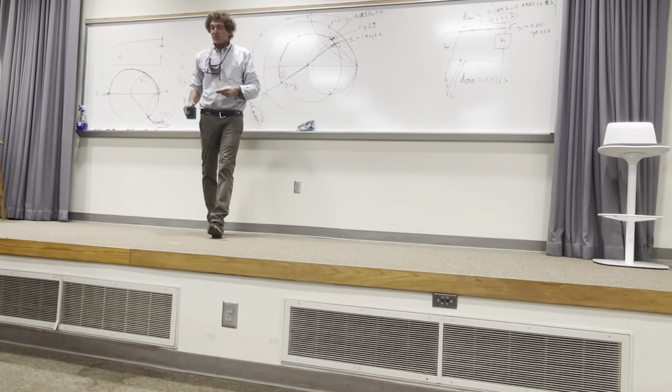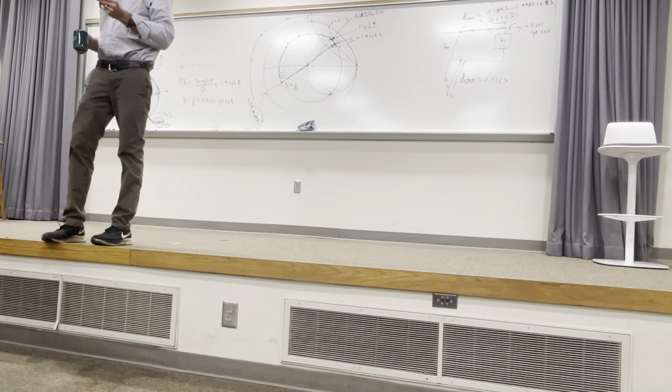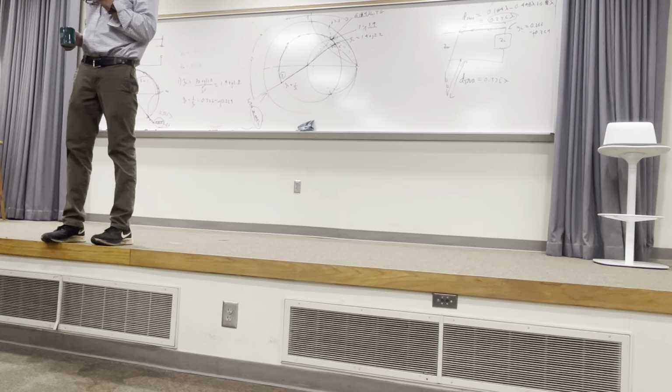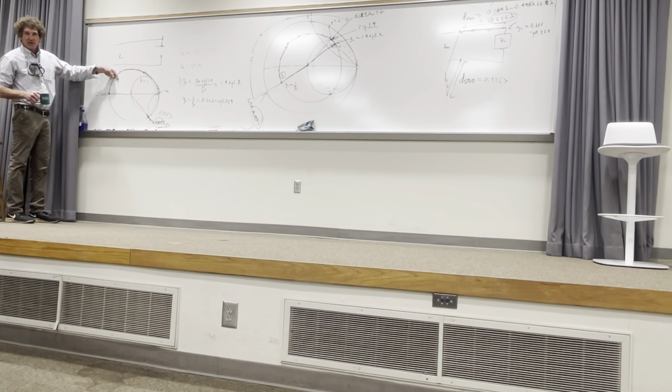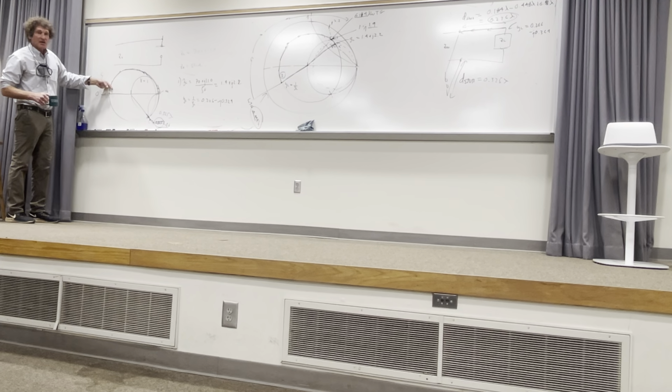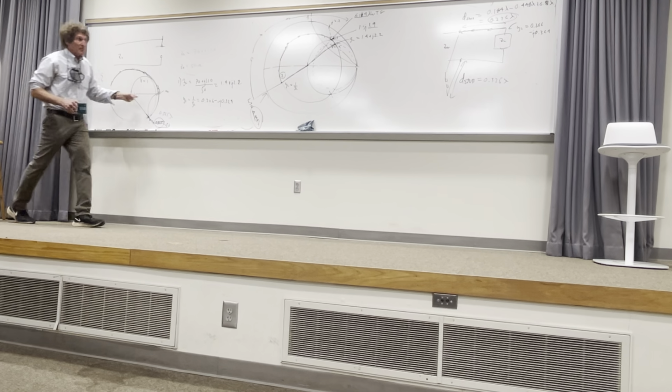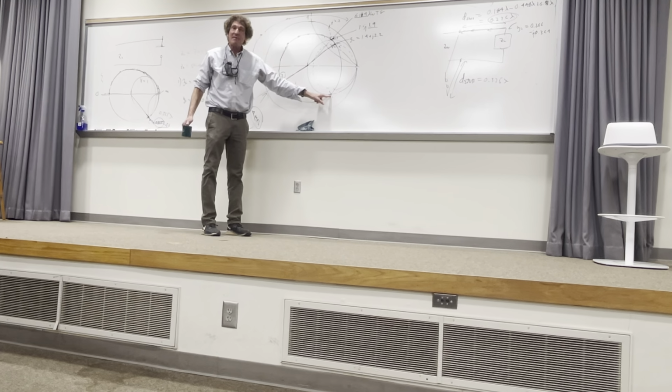I can go through the constraints. I could say, I want you to minimize the length of the open circuit stub. Now, the whole idea is this: that stub is either going to have a plus or minus J limit. If you come in with an open circuit stub, the first thing is a plus J. Any incremental length to that line gives a plus J. That means for this to be minimum, the point you would select would have a minus J here that you're going to get rid of. Y'all follow me on that rationale?